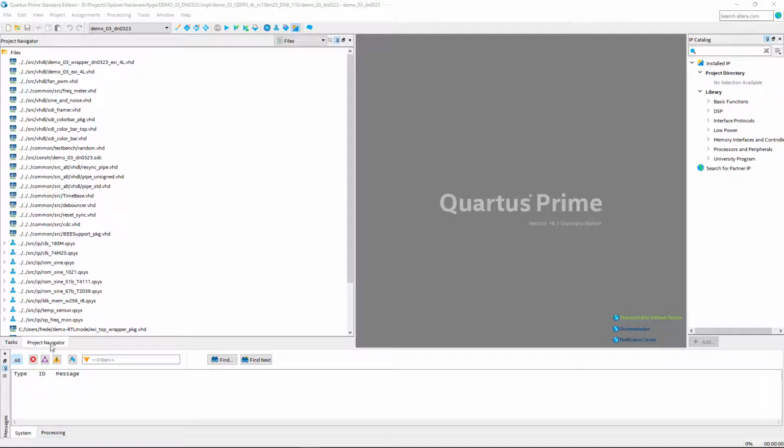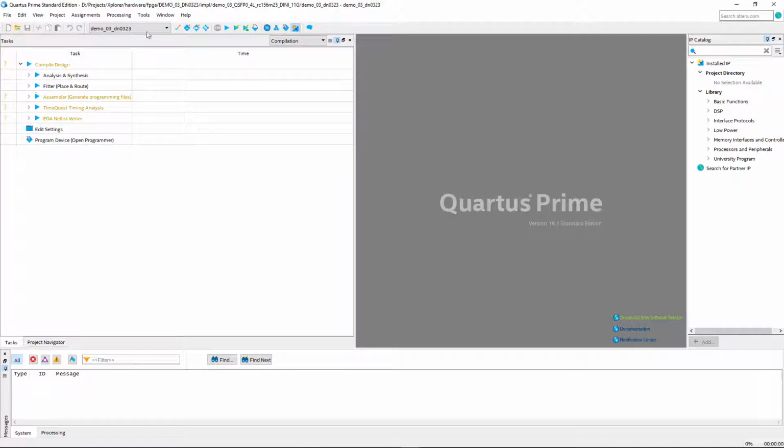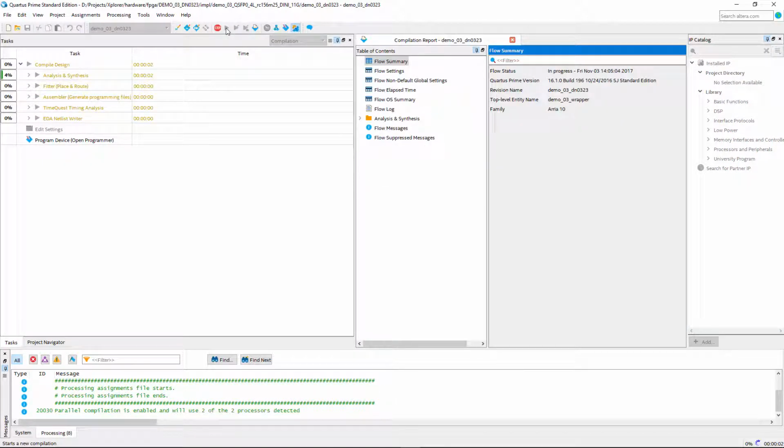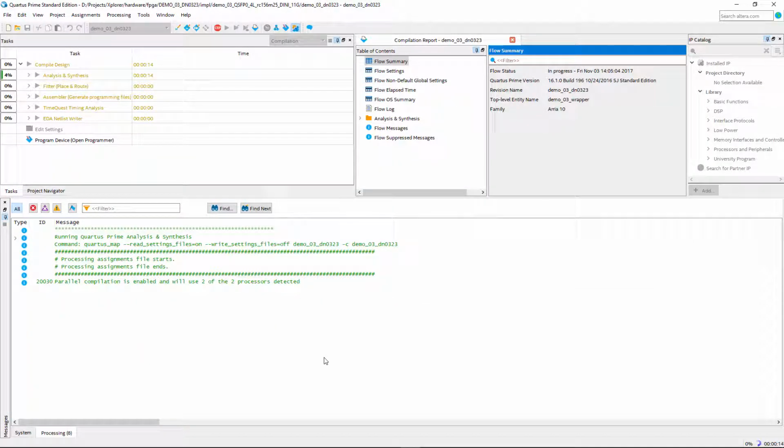After this, all we need to do is start the synthesis and implementation of the instrumented design. This process generates a binary file that can be used for programming the FPGA. The FPGA is then instrumented and ready for use with the exhaustive probe.